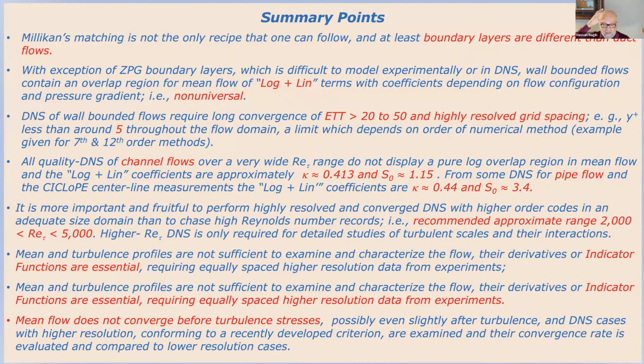And if you ask me the question, I might as well answer it now. The higher order terms all have 1 over RE tau in them. So they just disappear as RE tau grows. They're non-universal. ETT, Eddy turnover time, needs to at least get to 20 to 50. We're not quite sure if there is an exact recipe here.